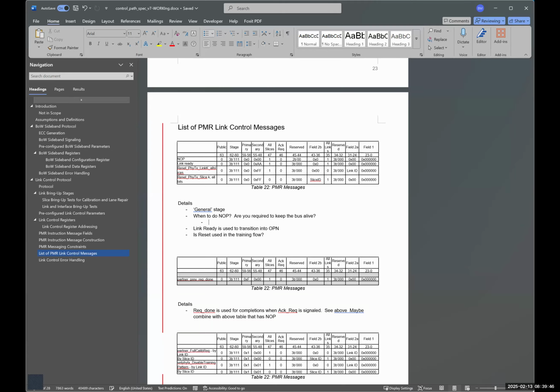It's just that the way we had all our internal CSRs and everything set up, it was easier to use a few bits of the register itself to generate the interrupt. That's the choice that I made. But I see what you're saying. I think it is all implementation dependent on how they want to let the software know that there is something available in PMR. That portion can be left as an implementation choice.